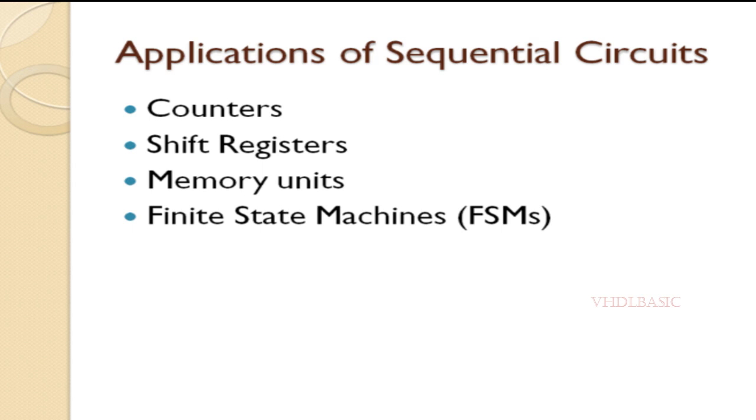In a combinational circuit, there is no internal memory or feedback mechanism. But in the case of a sequential circuit, it has internal memory and a feedback mechanism is also supported. The output is a function of input only in the combinational circuit. But in the case of a sequential circuit, the output is a function of the input as well as the previous output or previous circuit state.